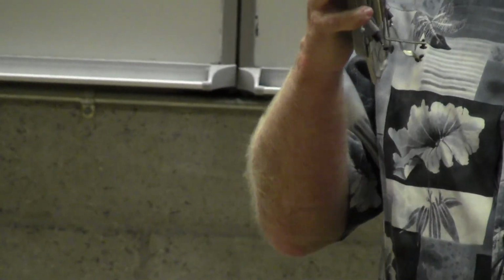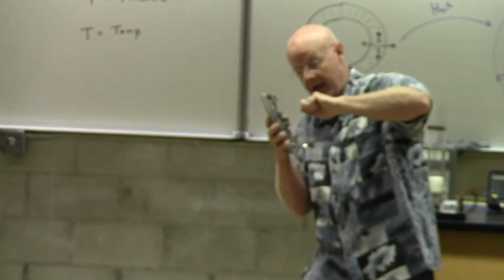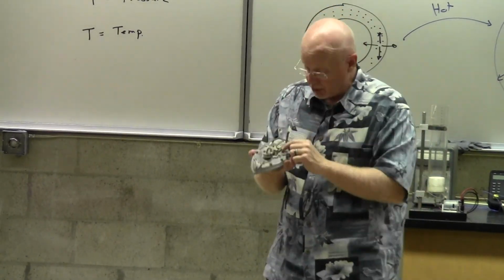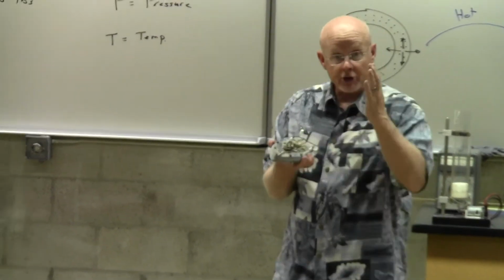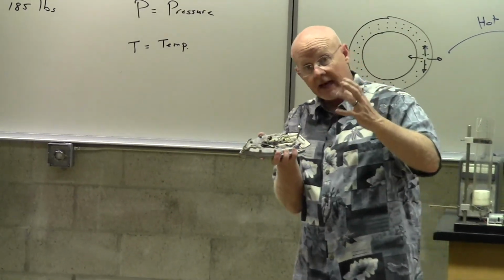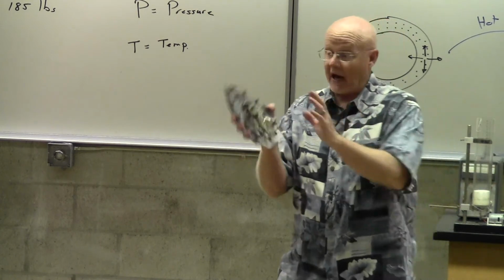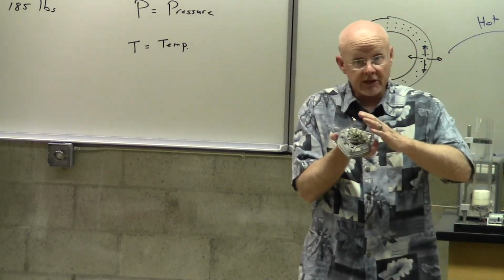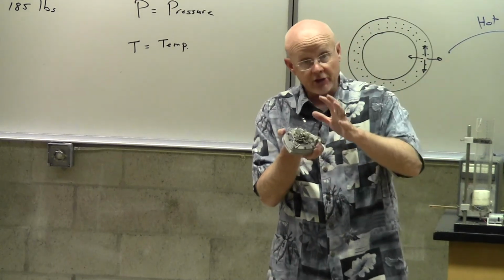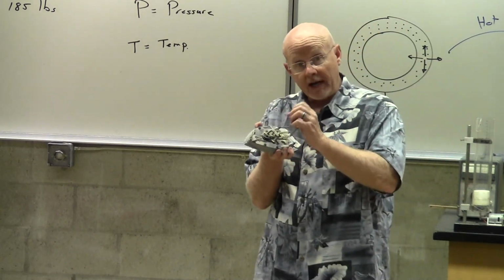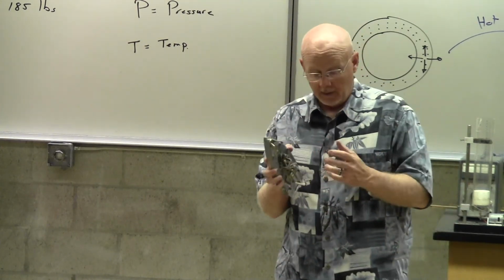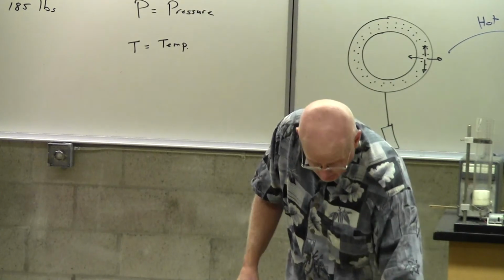But when this thing gets up to a certain temperature, which I can control with a dial on the top, I can set this for low heat, medium heat, or high heat. And so if I set it for medium heat, let's say, it'll warm up till it gets to about that temperature. Then it'll get so warm that that bimetal strip bends and breaks contact, turns off the electricity. Not that I turned off the iron, not that I unplugged it, but the mechanics in here, the thermal expansion, is being used. And so the engineers have designed it to say, okay, will this break contact at a certain temperature? And so that's what the medium heat is set up for.